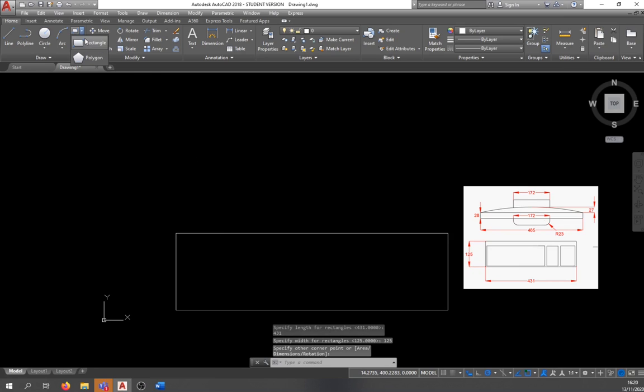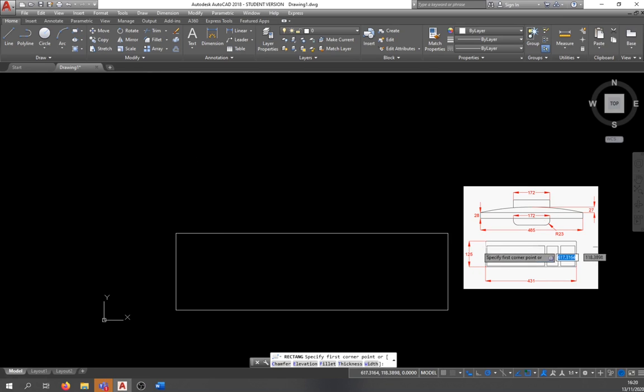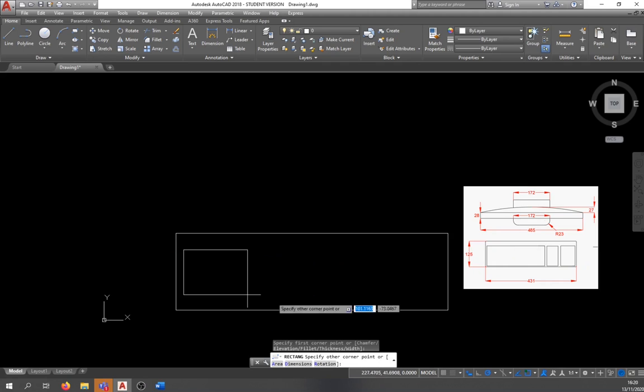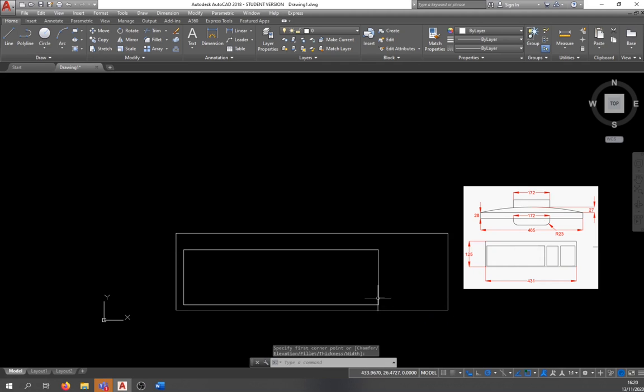Then I'm going to bring up a rectangle again and draw the internal parts where the keys are housed. Again, these are freehand drawn, so just draw them roughly where you want. A quick way, if you're using the same command over and over, instead of going up and clicking the rectangle each time, is to press spacebar, which will bring up the last command you were using. It's a handy way to speed things up a little bit.